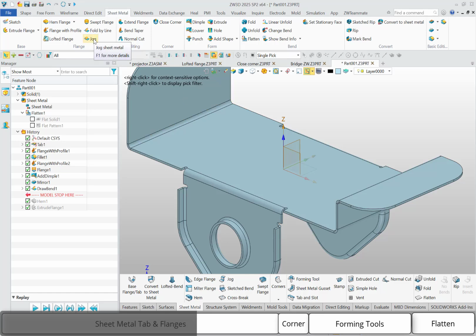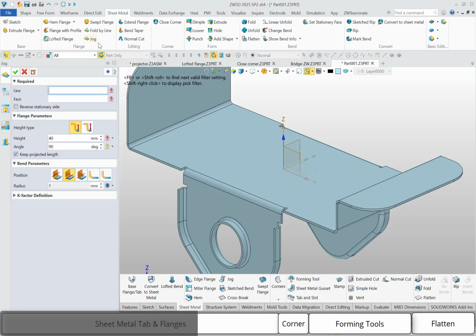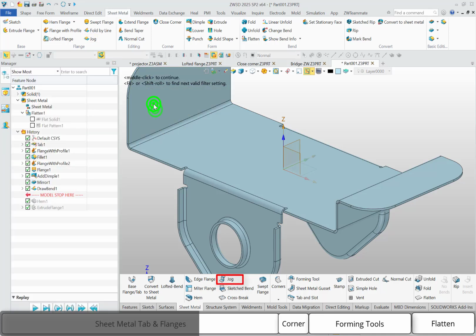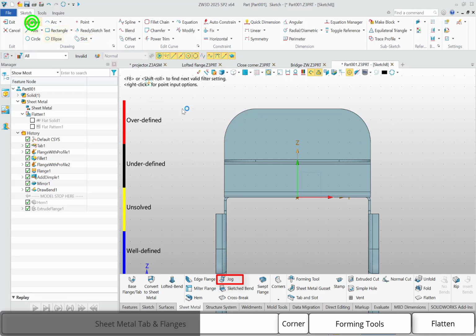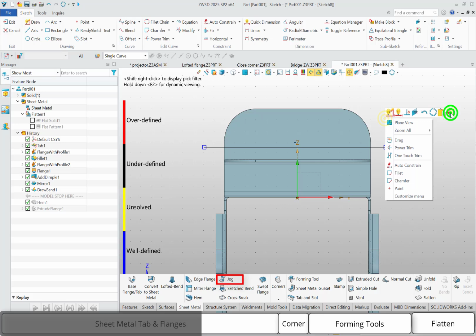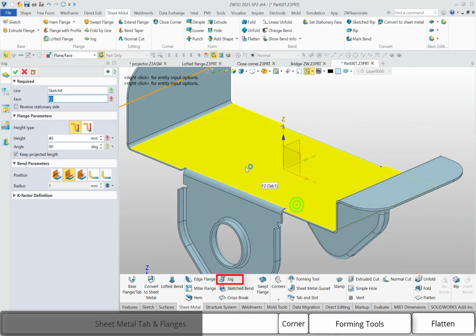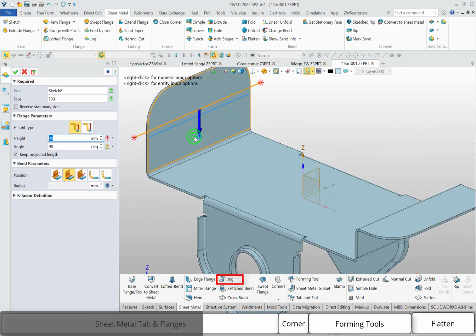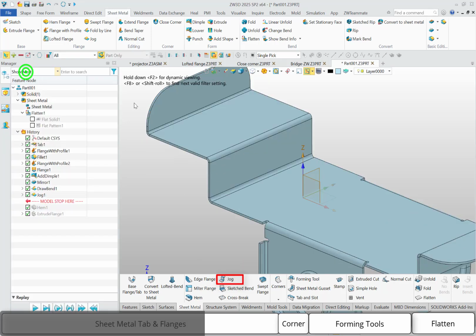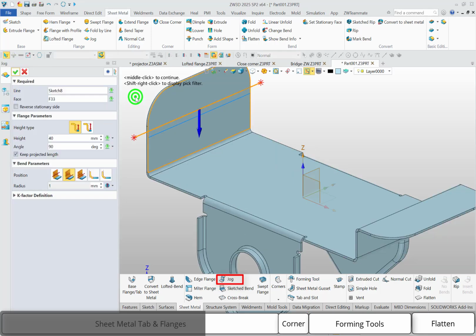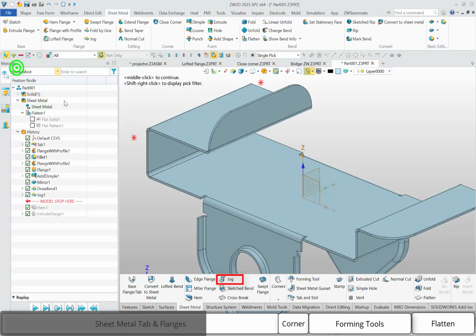And a similar command is jog. The main difference is its jog command will create 2 bends instead of 1. Here we also create a line and define the plane. Okay. Now we need to reverse the side. Okay, we'll get the correct result.